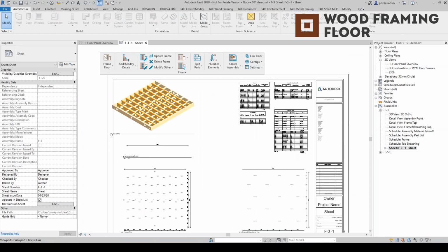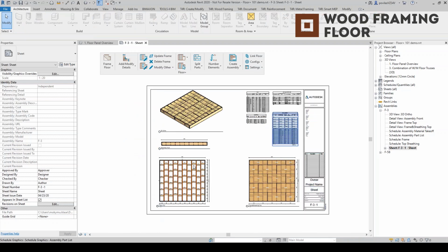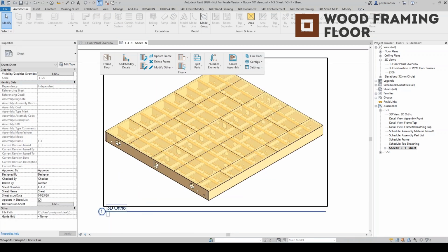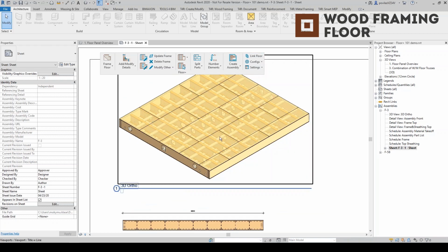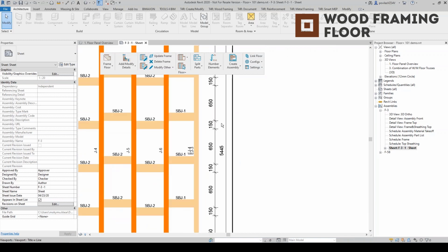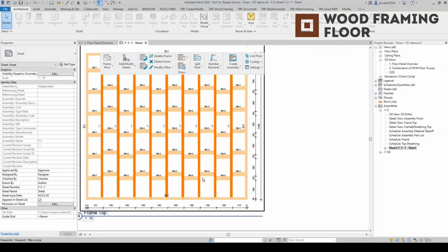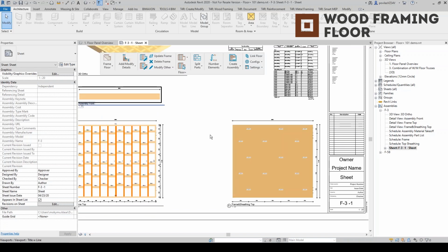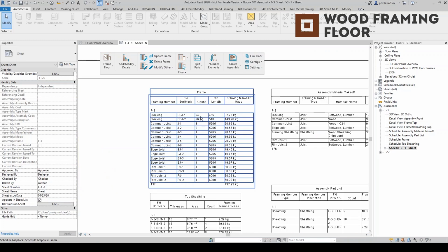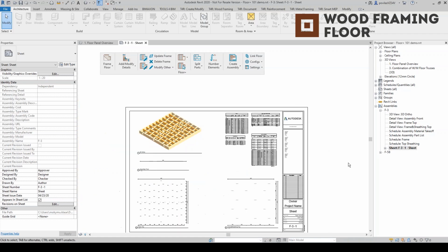Okay, so all of that is in place. I mean, there could be small inaccuracies, but once you set up your sheet template, you can reuse the template for the rest of your drawings, or produce multiple templates, of course. So here we go, our penetration holes are in place, sheeting both top and bottom layers are in place, dimensions put automatically. Okay, all those rules are again customizable. Each structural item is tagged. Okay, view is generated and placed on the sheet, and sheeting itself is in place. More than that, we have our schedules. Okay, there we go. So we'll go back to this view.